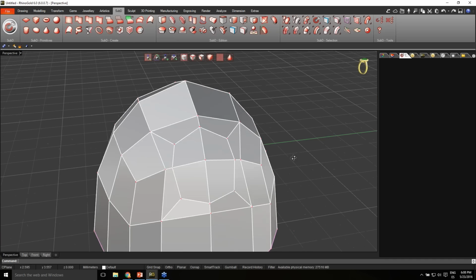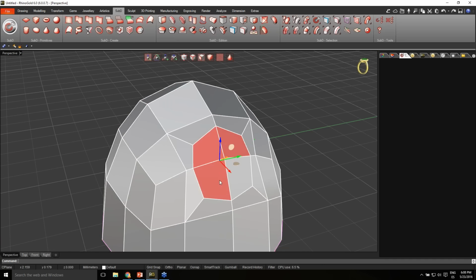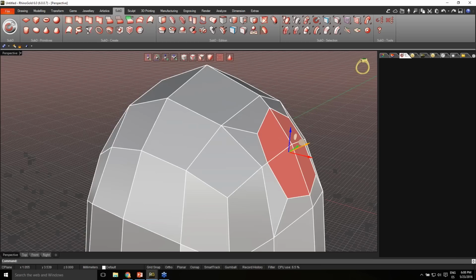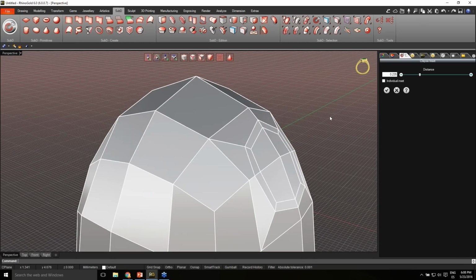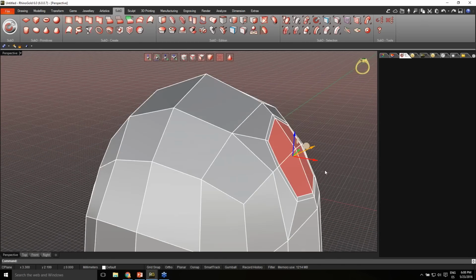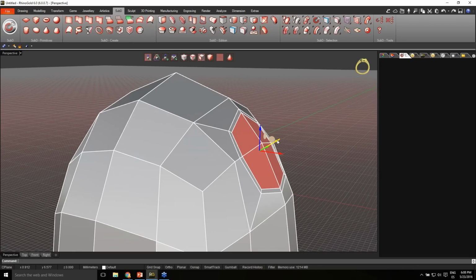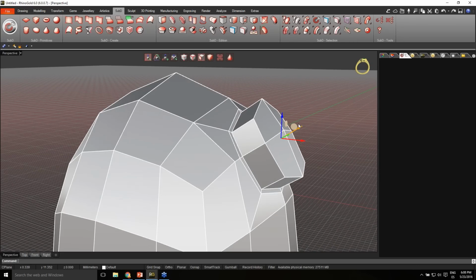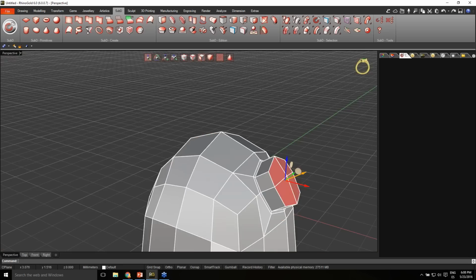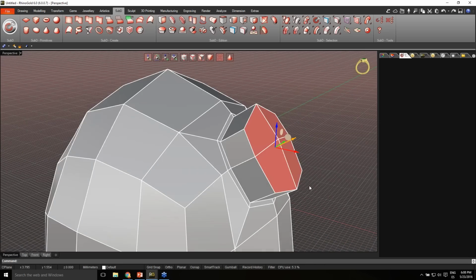Perfect. What I'm going to do right now is select these four faces that I have. I'm going to create a small subdivision, so I'm going to create an insert right here. I'm going to validate. I'm going to hold Alt on my keyboard and drag the gumball to create extrusion. This is another powerful improvement of ClayU 2.0.